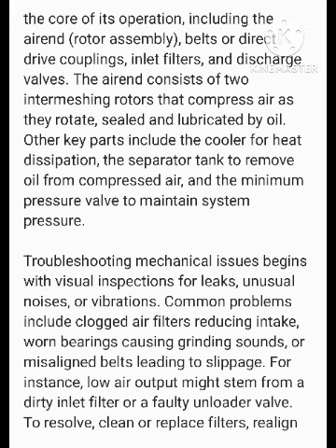Troubleshooting mechanical issues begins with visual inspections for leaks, unusual noises, or vibrations. Common problems include clogged air filters reducing intake, worn bearings causing grinding sounds, or misaligned belts leading to slippage.